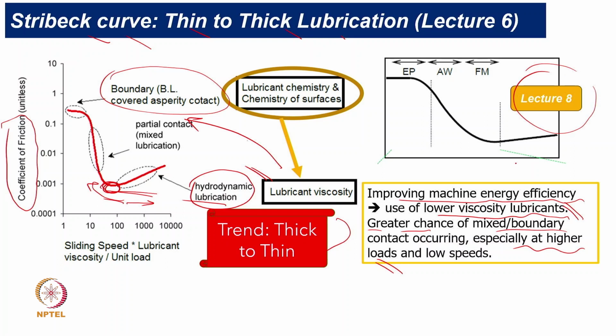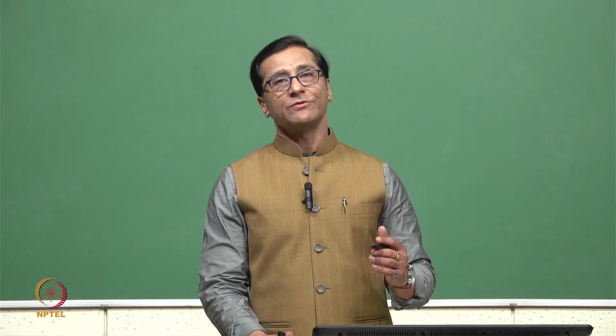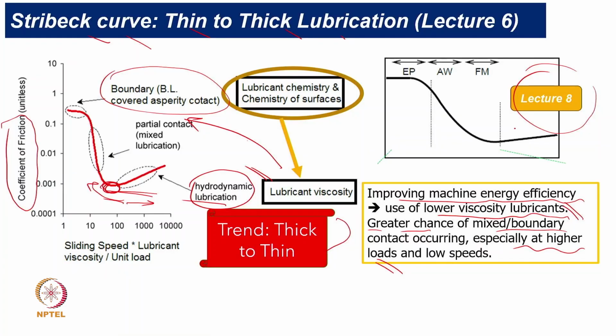We say very well, now it is very difficult to keep track of whether it will be hydrodynamic, mixed lubrication or boundary lubrication. So the complete oil should have everything, or be self-adaptive. Now if we have a low viscosity oil, and then we add FM, anti-wear additives, and EP additives, then whenever there is a situation, the low viscosity oil will be able to do justice to hydrodynamic lubrication. FM additives will be able to do justice when there is somewhat mixed lubrication.